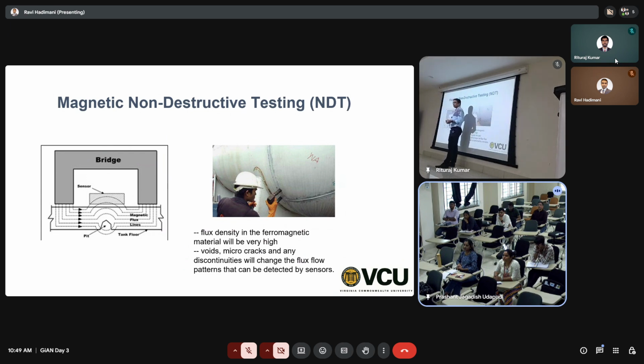This is a sensor, which is a secondary coil. Basically, the nice thing about generating and sensing magnetic field in a crude sense, okay, not the data recording, that's very sophisticated, but here it's a crude sense. Look at this, this is how you generate a magnetic field. It's this big. You just take an iron core, wind some copper wires, and supply some current to that wire. Depending on the number of turns and the amount of current, you can determine the magnetic field coming out of this big yoke, right? Iron core yoke. So you generate a magnetic field.